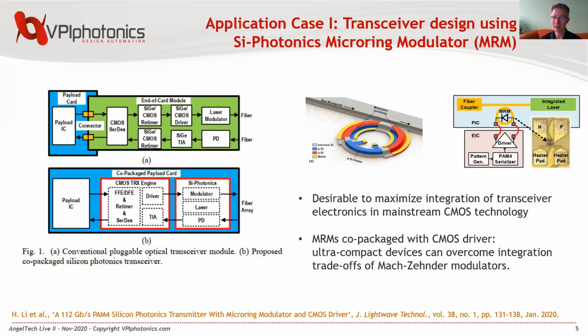We see on the right-hand side, at the top, the photonic integrated circuit model with a laser and the microring modulators. And here we see the electric integrated circuits with the drivers and serializers. So if you want to simulate the whole structures, then an EOE simulation domain would be needed, including the detailed modeling of the electrical parts.